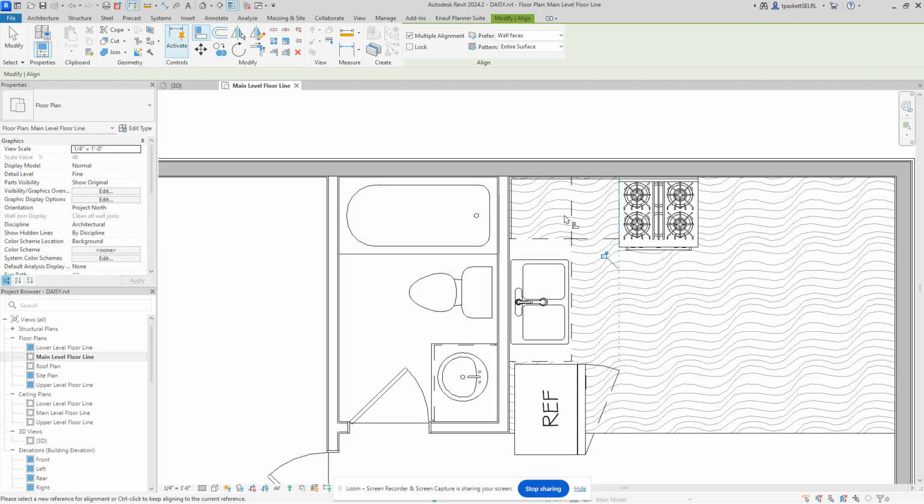Okay. So here in the view, you have a section cut. If you just cut a section right through that part right there, then you can right click, go to view, and there's your seat. Select it again, pick a new host. It has to say I'm not in the right plane, so okay, fine. Then select it, go back to the main level, host. It's a little temperamental. You have to make sure it's highlighting that countertop.